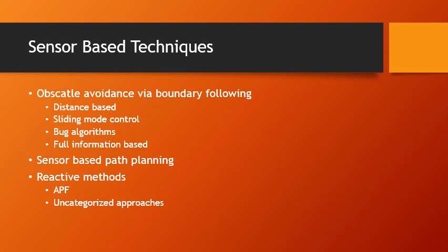APF computes the control input online based on available information. Introducing unicycle kinematics, local minima avoidance, closed-loop performance, limited obstacle information, and actuator constraints are improvements that are commonly considered. In uncategorized approaches, a safe maneuvering zone is based on the kinematic unicycle model; the vector field histogram directs the vehicle towards sufficiently large gaps between detection rays. Probabilistic convergence by use of deterministic tangent bug algorithms is considered in this section.